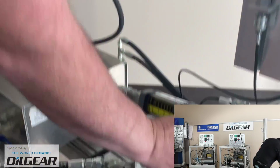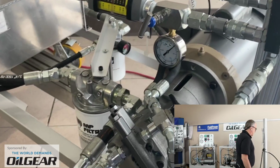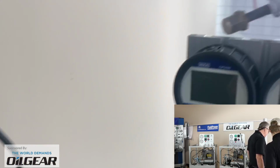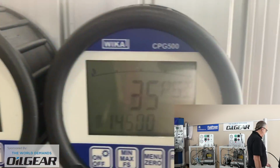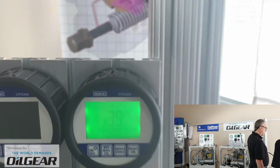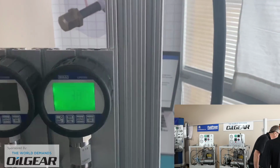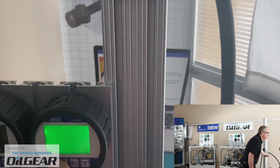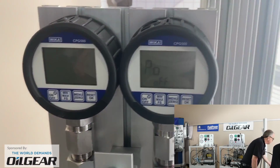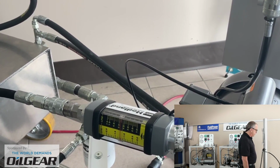I'm just going to make sure that my flow is all the way open here. I'm pretty sure it is. Okay, and we can see that we're pumping at 1.2 gallons per minute. This one does not have a maximum volume stop, so this one's only going to have pressure compensate. With lots of flow taking place right now, we're not in the right state to adjust the pressure compensator. The pump's outlet line is simply pumping back to tank, right back through the filter, so it's a pretty easy flow path. Not a good state for adjusting the pump's pressure compensator at all.